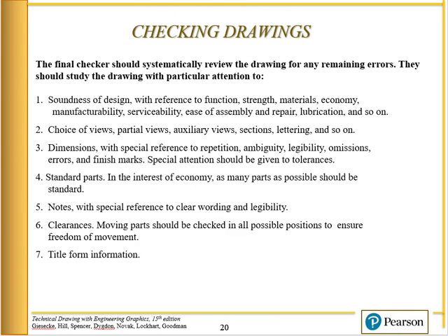Checking drawings. In most companies, they'll have a drafting checker. A drafting checker is somebody who has a lot of experience in drafting, and he would systematically review the drawing for any errors. He would look for soundness of design with reference to function, strength, materials, economy, manufacturability, serviceability, ease of assembly and repair, lubrication, and so on.